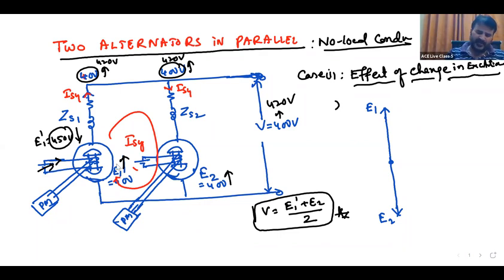During parallel operation, an overexcited machine will always be demagnetized. An underexcited machine must be magnetized. Then only is there voltage stability. The overexcited machine has to be demagnetized and the underexcited machine has to be magnetized to reduce the difference between these two. Who is doing this? Synchronizing power is doing it. Okay.